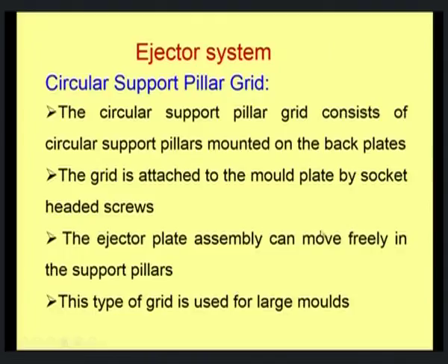The ejector plate assembly can move freely in these support pillars. They can move; the ejector plate would normally move when the mold opens. This type of grid is used for large molds, unlike the inline grid mold, which is meant for small sized products. This circular support pillar grid system is used for large molds to prepare a large sized product.